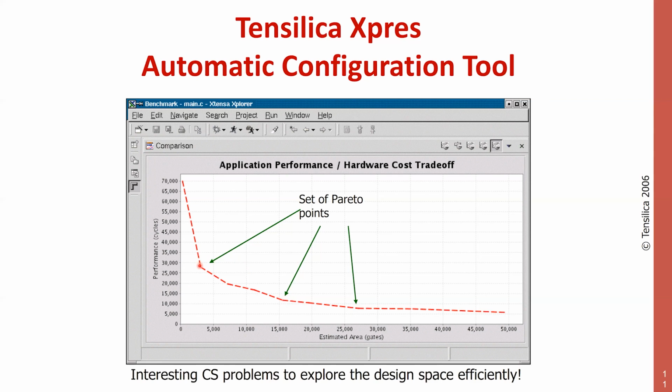These are all Pareto optimal points here in these corners of this spline. They are Pareto optimal because, for instance, between these two, one is better in area, right? This is much smaller than this one, but this is much slower than this one. So one point is better in area, the other one is better in timing, and therefore they are all equally good in some sense.